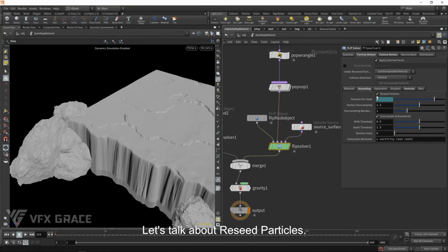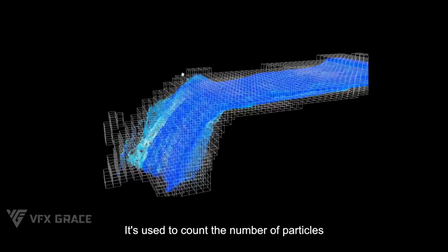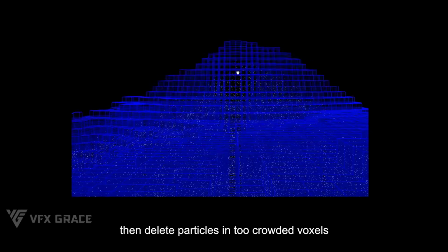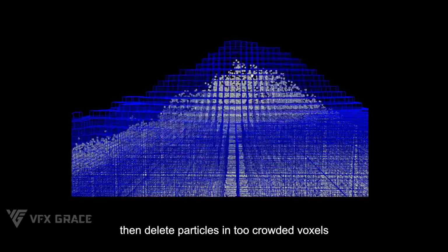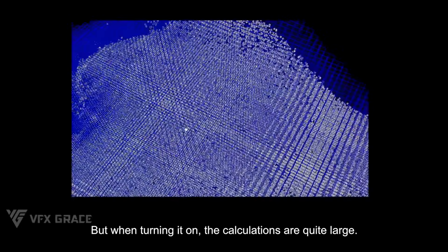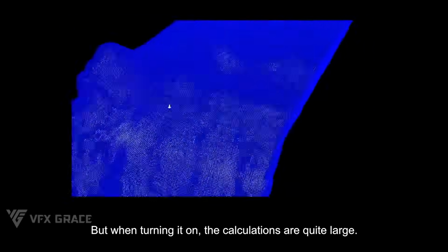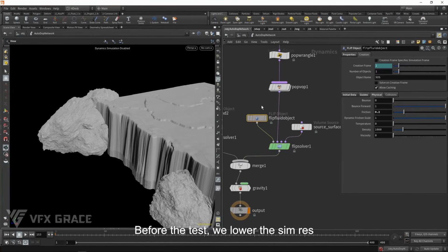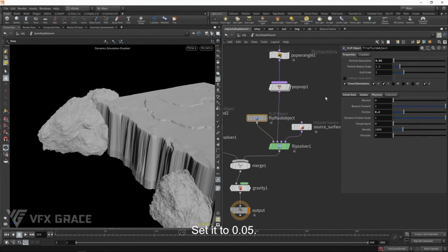Let's talk about reseed particles. It's used to count the number of particles inside each voxel, then delete particles in too crowded voxels, and create more particles in sparse voxels. But when turning it on, the calculations are quite large. So we can turn it off and see if the simulation can be speeded up. If it speeds up the simulation and it makes little difference in effect, we can turn it off. Before the test, we lower the sim res to speed up the simulation a bit. Set it to 0.05.